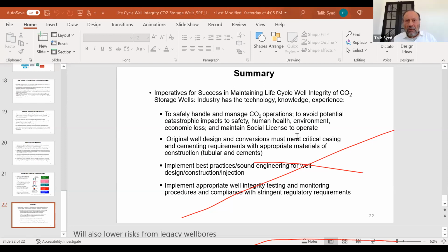Casing, yes. See, strength is not really a problem, but some of the casing that are being used are L80, but with extra strength for CO2, and also N80. It depends upon what the depth is, and Regularity, for instance, is doing a lot of work on that on a global basis. I'm sure if you contact Regularity, they've got offices globally, they will tell you about some of the tubulars that they're looking at specifically for CO2. But it depends upon the well and what the characteristics are.